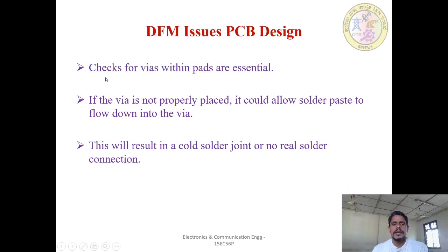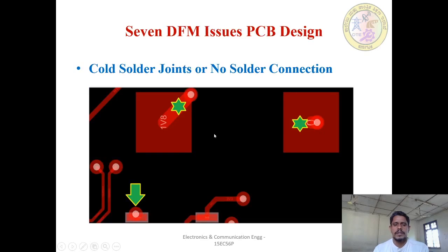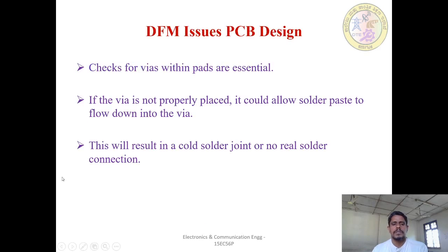DFM issues again. Checks for vias within the pads are essential. Is the via on the pad essential here or not? Actually, it is not essential here. If the via is not properly placed, it could allow solder to flow down into the via.